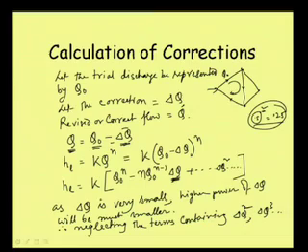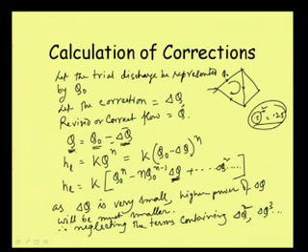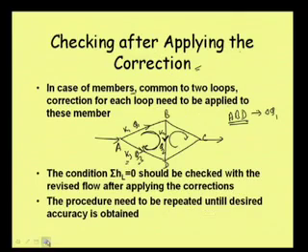But if our correction value is negative, then for a clockwise flow it should be added. That means q0 minus, then minus delta q. If the value itself is negative, that will have to be added. So these are some critical points that we need to consider.